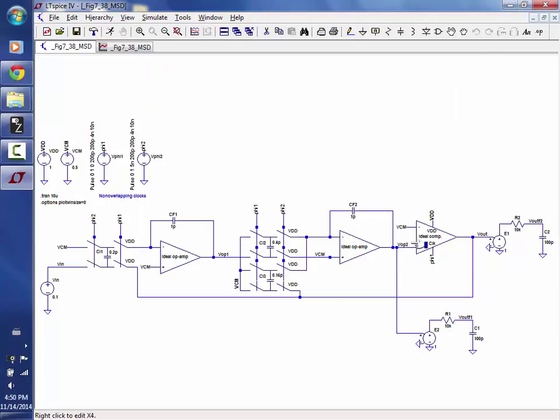So the only time, remember this signal here is swinging, right? And if we make this capacitor smaller, then the signal is going to get bigger. Yeah, so, ideally, if it's an ideal comparator, you could get 1 microvolt here, and the output would change. So, yeah, infinite gain, right?